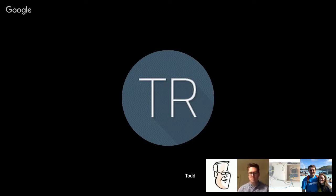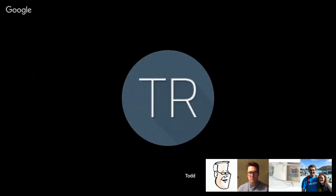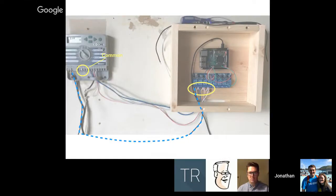Sorry, what did you do with the other lead that comes from that power adapter then? So nothing. That other lead, this controller has some internal workings to connect the common to the other lead, just behind the controller box. So I really didn't have to do anything to that. I just needed one wire from one of these 24 volt leads, and then plugged all the zones in, and everything worked.